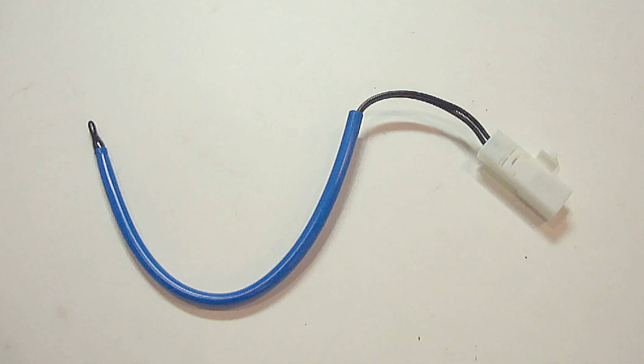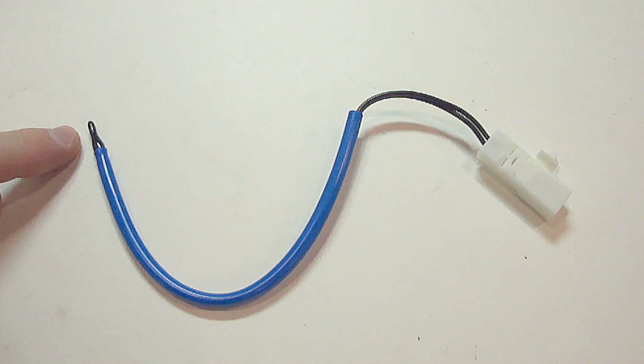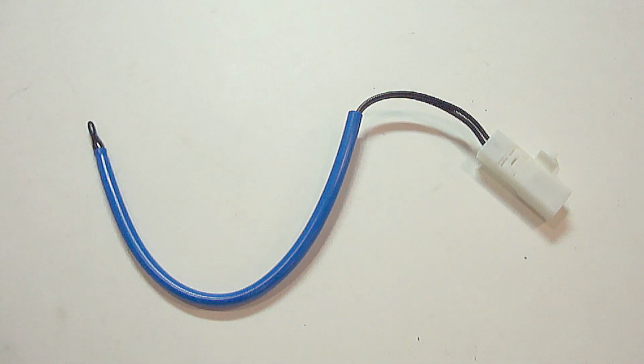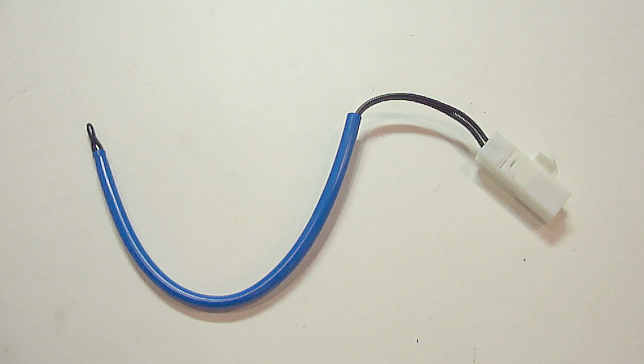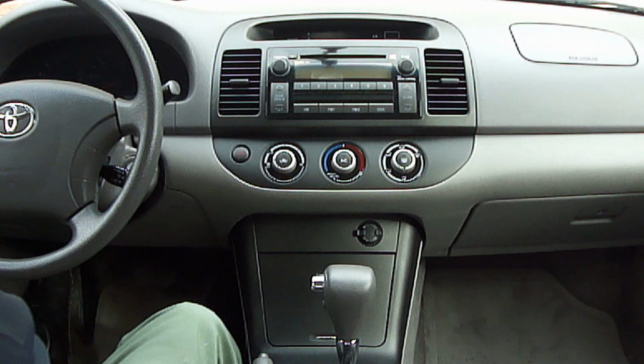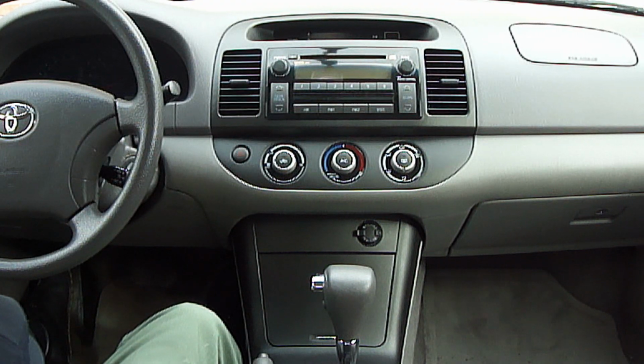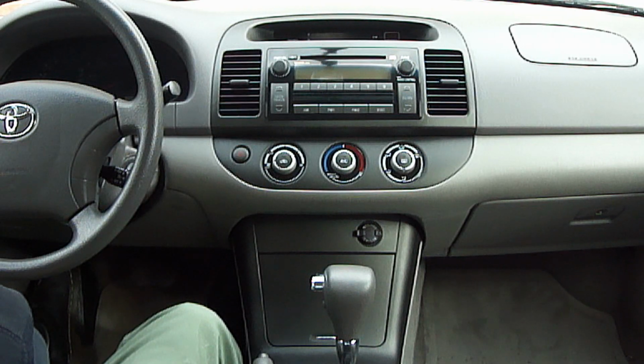Here's an evaporator temperature sensor, and this is the temperature probe. The way the sensor works is it sends different readings based on how hot or cold the temperature probe is. This information is then used to turn the compressor clutch on and off to maintain cabin temperature and to prevent the evaporator from icing up. To determine the exact location of the evaporator temperature sensor, you'll need a repair manual, or you might be able to find it by doing a Google search.